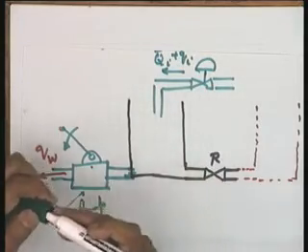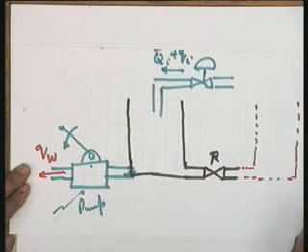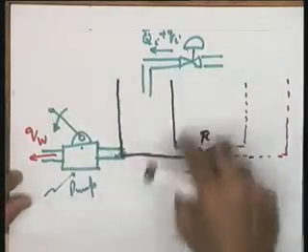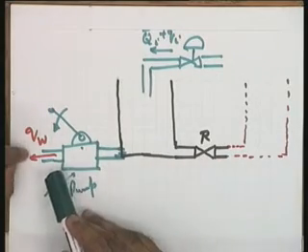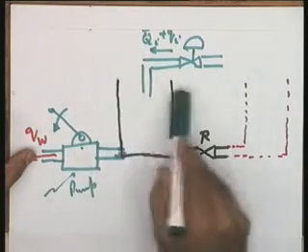Yes, please. So this QW, isn't that also a controlled variable? Because you can control the pump and hence control the outflow of water to some extent. Yes, provided you are using it. It depends, you see, when you are given a particular situation, it depends on your control configuration, the designer's control configuration. If you are using this as the controlled variable, then that flexibility which the user may require, that sometimes you require a bulk of liquid, certain processing, let us say some composition change is going on in the process, intermittently you require that, so that quantity will not be available to you if you are using this as controlled variable to control the height of the liquid in the tank.